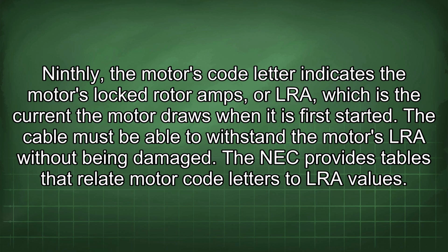draws when it is first started. The cable must be able to withstand the motor's LRA without being damaged. The NEC provides tables that relate motor code letters to LRA values.